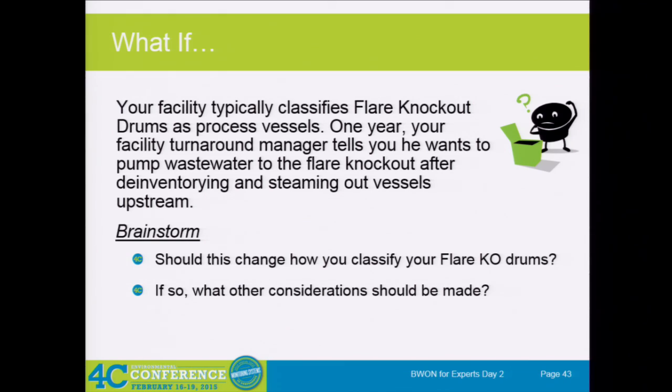There's a difference. A flare knockout pot is to knock out entrained water in the vapor streams that are venting to the flare. As a safety device process vessel, it's not designed, or typically supposed to be designed, to receive liquid wastes. If you start doing activities like this, do you think it would change how you classify your flare knockout drum? If you start pumping wastewater to it or de-inventorying liquid waste to it? Yes.